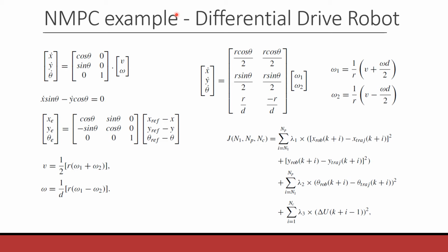The cost to be minimized by the predictive controller is typically associated with the dynamical change of the system over time. In the trajectory tracking problem, the cost function must penalize the difference between the pose of the robot and the pose of reference given by the trajectory generator. Additionally, the cost function has a term that penalizes the control effort. Each of these penalizations is associated with a weight that defines the proportion of penalization over the global value of the cost function.